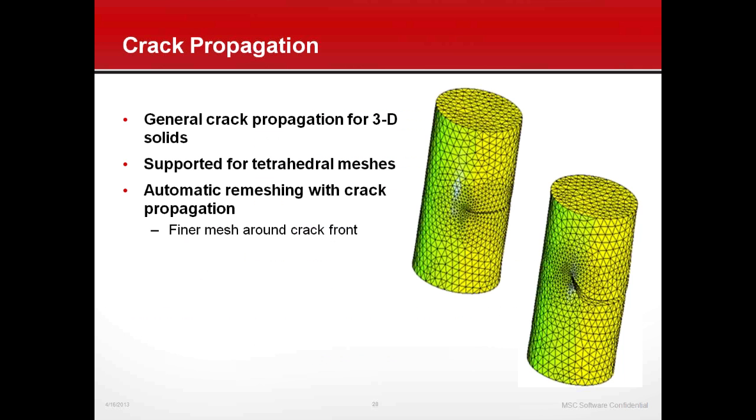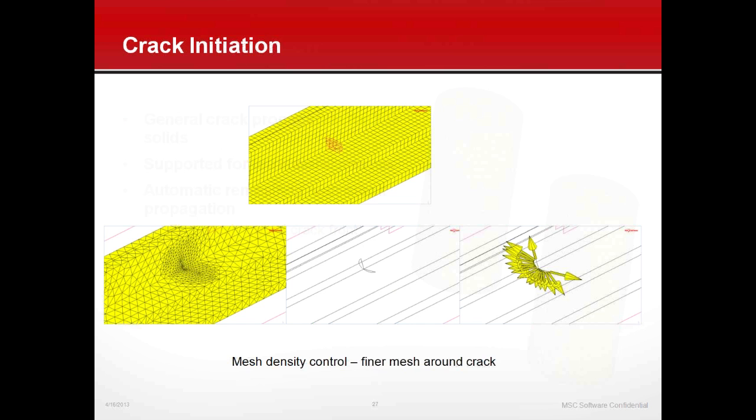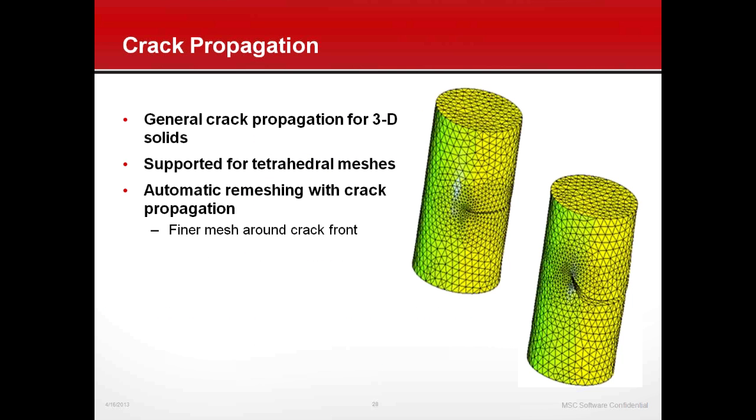This brings me to the final part of the presentation, which is about the new features for crack propagation. We have already seen examples where we grow along element faces, and here I show some examples of growth in general directions, I should say, arbitrary directions with remeshing.